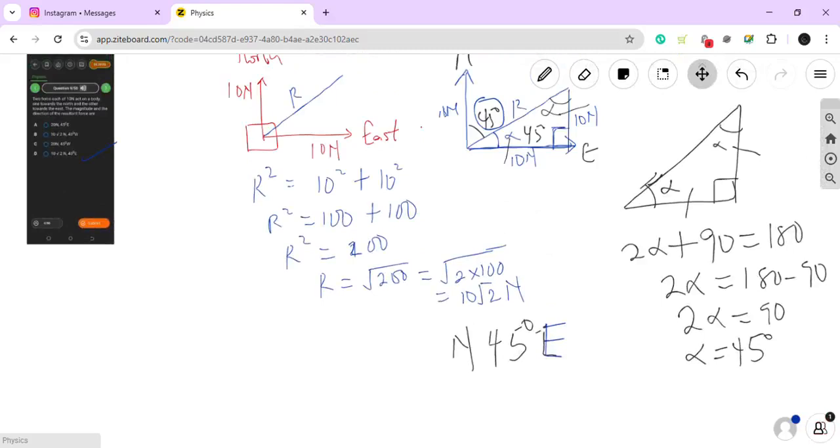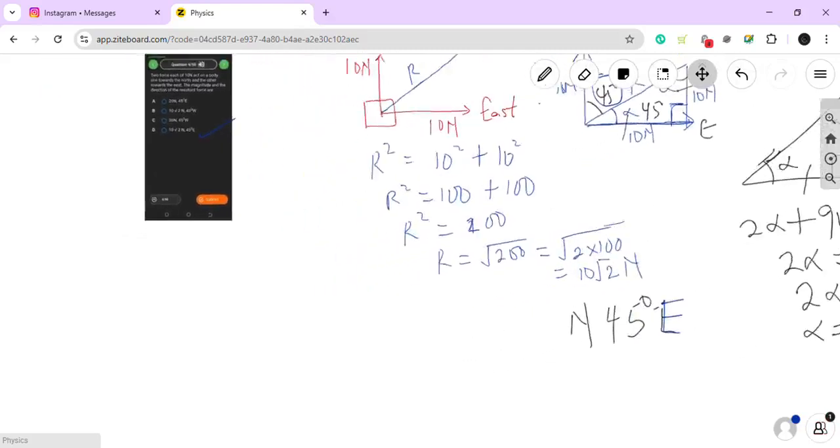So after doing that, you can now make use of surveyor's bearing or compass bearing. Assuming when you do it, you get something like 135. 135 normally will come from here to this place, right? Surveyor's bearing will tell us that this is 135 degree.